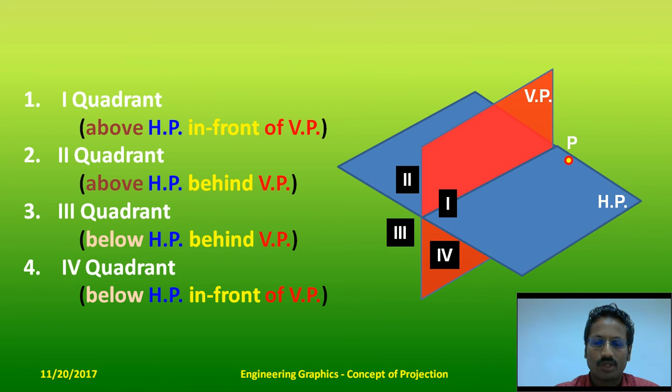There's a sign convention of rotating this horizontal plane. This horizontal plane has to be thought of as a single extended plane. These are imaginary planes of infinite dimensions and sometimes thought of as transparent in nature also, so that it's going to be see-through, something like a window glass. And the horizontal plane has to be rotated in such a fashion that when the object is kept in the first quadrant, then the top view of the object is going to come below the reference line. That's going to be the rotational direction of the horizontal plane. We'll see shortly about that also.